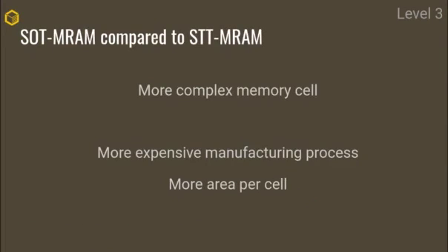Now, on the downside, SOT-MRAM compared to STT-MRAM, as you might have seen from the representation we saw earlier, has a more complex memory cell design, which means that it needs more masks to be made, and so has a more expensive manufacturing process and requires slightly more area on the die per cell. Also, there is the use of heavy metals involved, which complexifies and adds an additional cost.